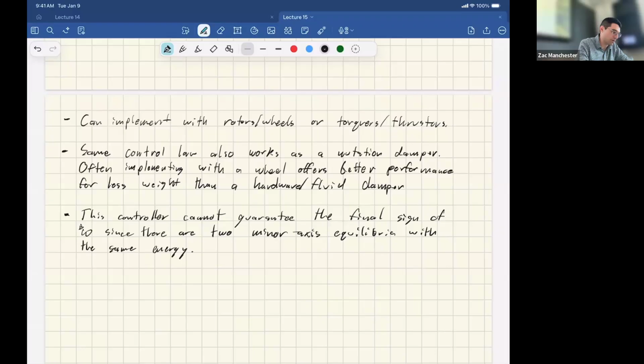All right, so usually spacecraft have 4 wheels at least. And 4 is kind of standard. Some have more, like Hubble, for instance, I think has 6 or 8. If you really care about pointing, you'll have more, but 4 is pretty standard.